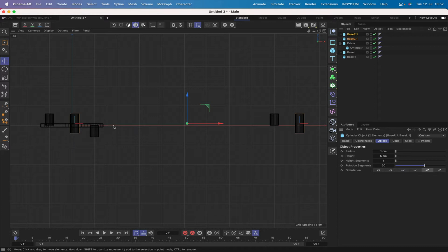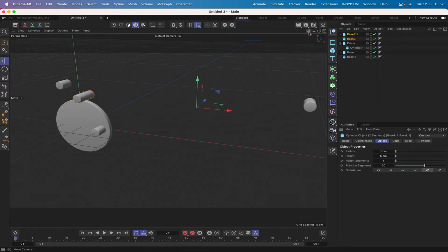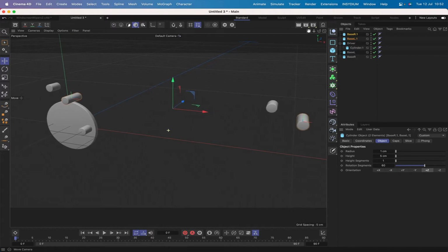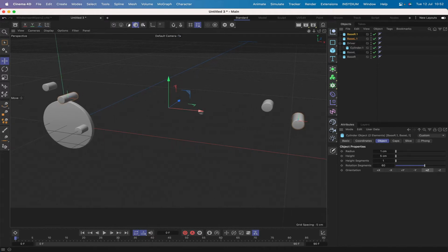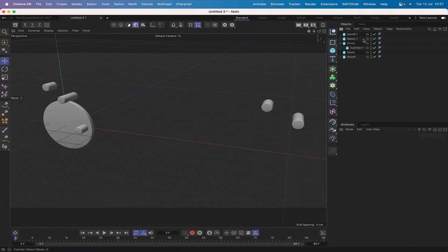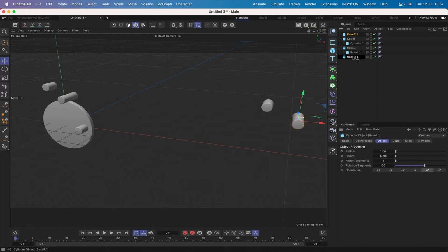Okay, that's all good. So hit H so that we can see everything again, and we've got all of our joints and pivot points and everything else set up ready for our arms. So the next thing we must do then is to actually create the arms. One thing I'm going to do before I go any further is group this into here and this into base R, and I'm simply going to rename these 1L and 1R. That's fine. That's all I need to do there.